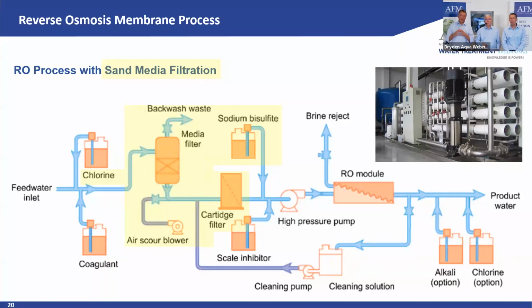So this process of natural selection, where we always remove 99.99%, but you always have a few survivors. In the long run, you will grow even bigger, stronger bugs. You will have more biofouling problems. Let's say you're not interested in AFM. One takeaway, if you have this situation: do shock chlorination. That's a lot better. Bugs are like human beings, they like to have always the same conditions. So it's much better from a biological point of view to do shock chlorination than to make it permanent.